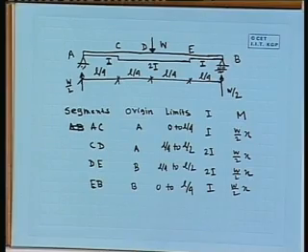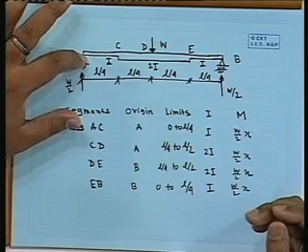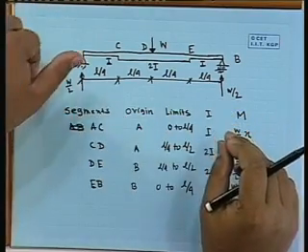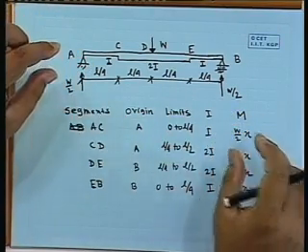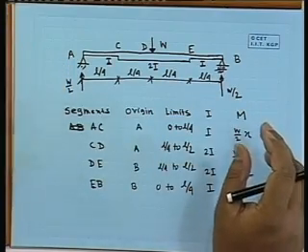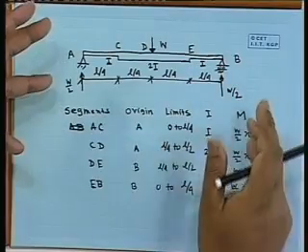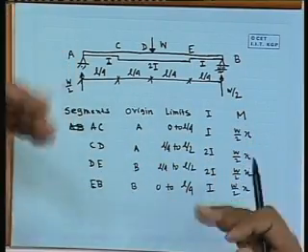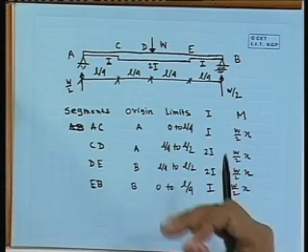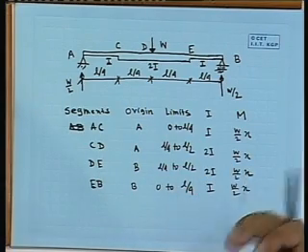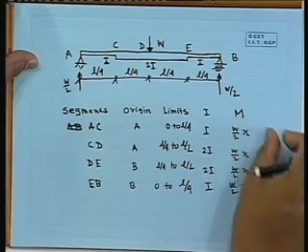Now, once that part is there, small m in a similar manner we have to write, right. Small m here we are interested in finding out the slope at A, meaning we have to take the beam and put a moment here and we will get the moment expression. So, the entire beam will get one moment expression, but as M has 4 segments, there also for small m we have to take 4 segments, right. Now, we can put the small m here.